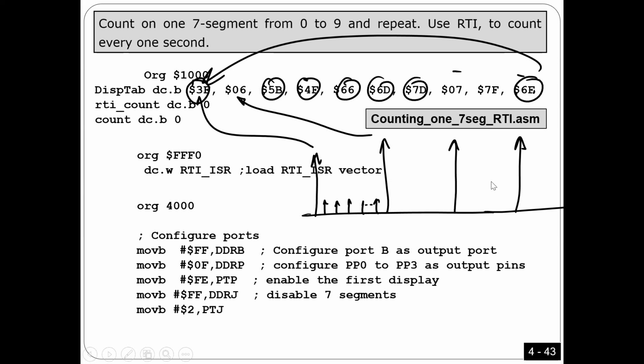That's why this should be done by using RTI, and it cannot be done by IRQ. IRQ is only for when you have an event, or you push whatever event you define. Every time you have an event, you need to trigger an interrupt. So this is completely different. If you want to do periodic operations, you have to do it using RTI. Is that okay, guys? Any questions?